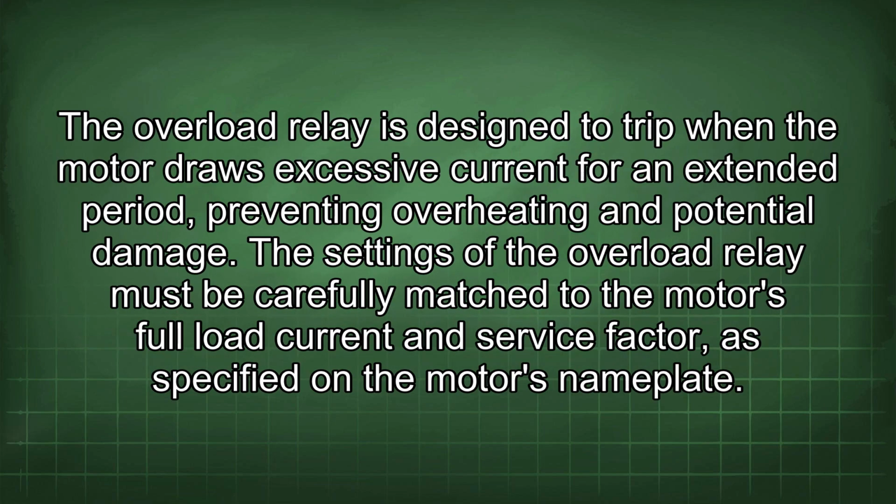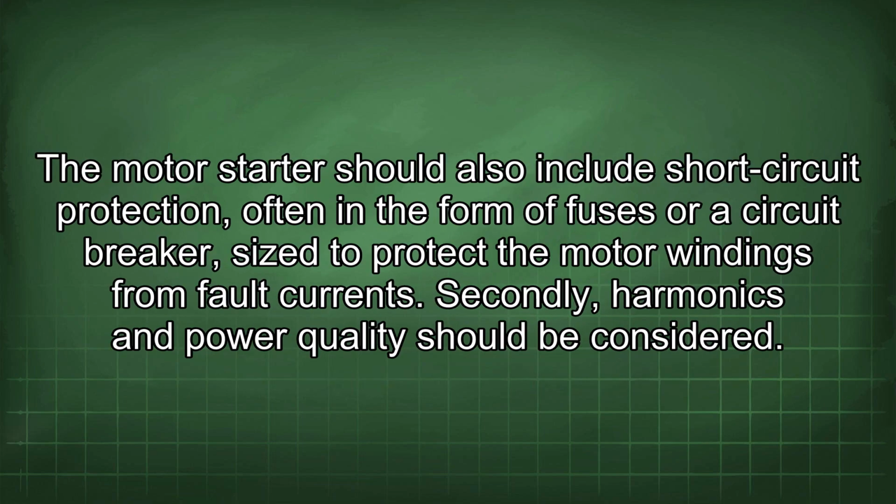The overload relay is designed to trip when the motor draws excessive current for an extended period, preventing overheating and potential damage. The settings of the overload relay must be carefully matched to the motor's full load current and service factor, as specified on the motor's nameplate. The motor starter should also include short circuit protection, often in the form of fuses or circuit breaker, sized to protect the motor windings from fault currents.